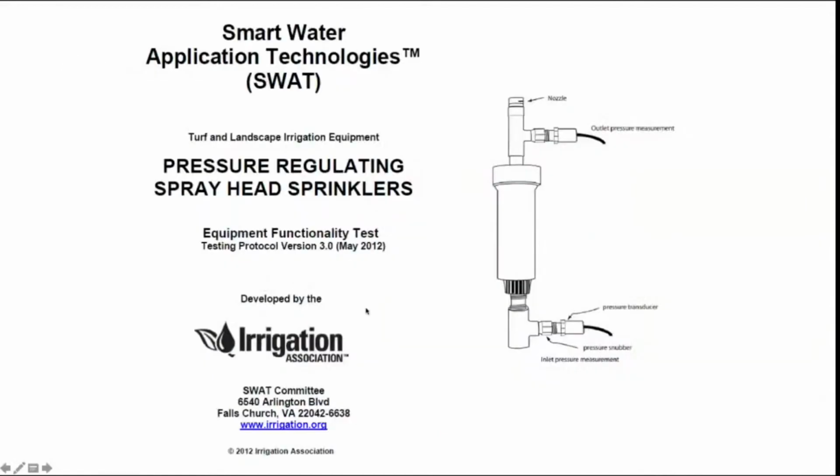we actually did a study on this at NC State. We took some manual heads, took the nozzle off, inserted a T adapter, measured the inlet pressure and the outlet pressure, and recorded that so that we could set up a test that others could follow to evaluate these spray heads that come on the market.